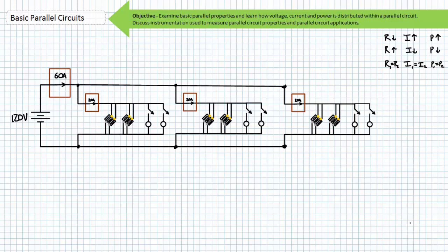Individual breakers leading from that garage sub-panel can then be used to functionally isolate these branch circuits. You should be able to shut down a system in a logical order, allowing necessary maintenance procedures to be performed without compromising functionality of the whole system. Imagine if you had to shut off the whole International Space Station to fix an outlet in some astronaut's bedroom. Ideally, you should be able to shut down just that bedroom and keep the rockets rocketing, the heaters heating, the air pumps pumping, and the Tang cooler tangy.